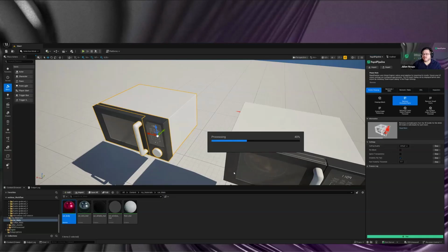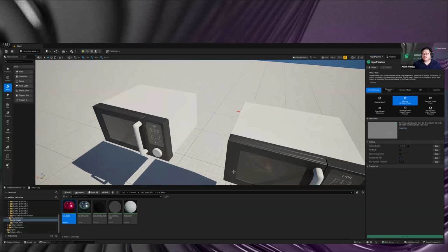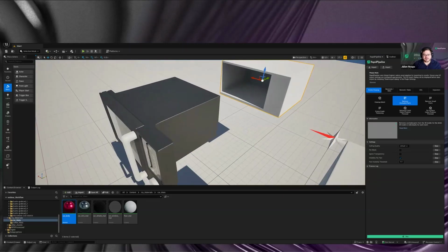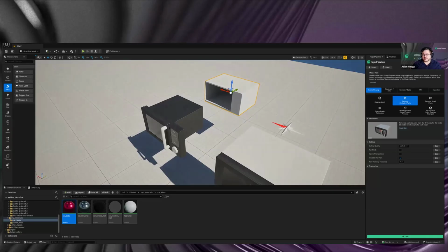What we recommend actually when you have a really large CAD assembly and you already know that you don't need the interior geometry, you can activate that option on the CAD import as well. There's a little Boolean flag for that with default settings, basically. So yeah, we basically just did exactly reproduce the result we have here in the middle.